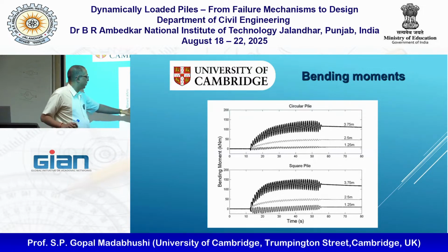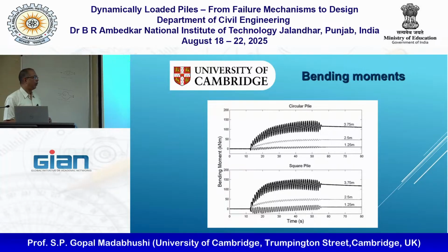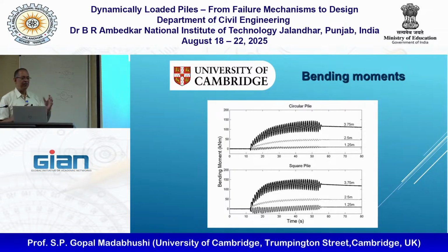So anyhow, the bending moment is the same, but the flow pattern is different. What that means is, although I attract the same load per pile, where the load is coming from in the soil is different. This one depends on a lot more volume of soil applying smaller pressure, whereas this one is very focused but with higher pressure. So the sum is the same, but the volume is different. Okay, that's the extra bit I wanted to say there.